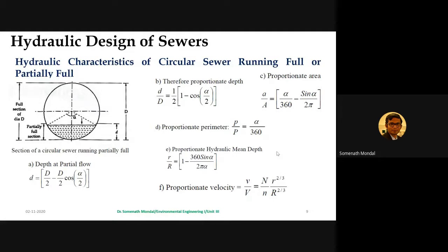That is one-third of the average flow I mentioned before, and a velocity of about 0.9 to 1.2 meter per second should be developed at the time of average flow. So these are the values which are very important, and they should be remembered. The velocity should also be checked for the limiting velocity, that is, the non-scouring velocity at maximum discharge. So this is very important.